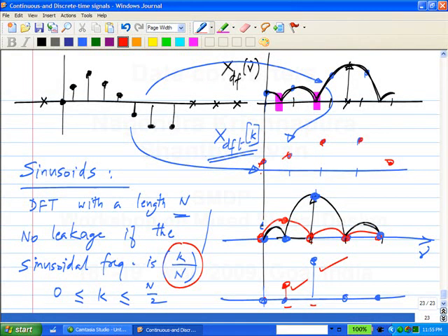Now how exactly you do this is by having two signal generators. See, the sampling rate is set by the clock. So your A to D will have the clock input and the signal input. Now the two signal generators which are generating the clock and the signal should be synchronized. Then you will be able to set the frequency to be some ratio like this. So this is one possibility where you have the freedom of selecting the frequency.